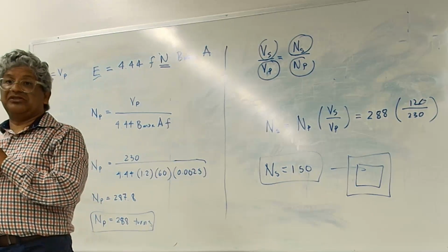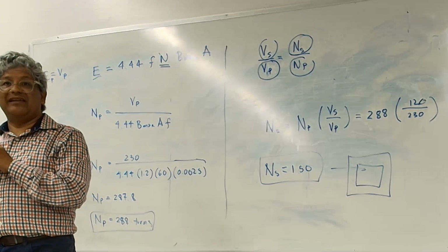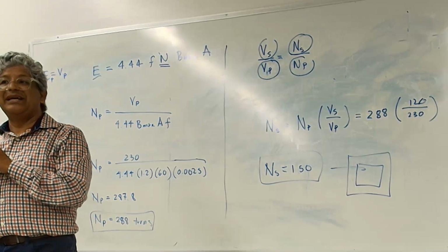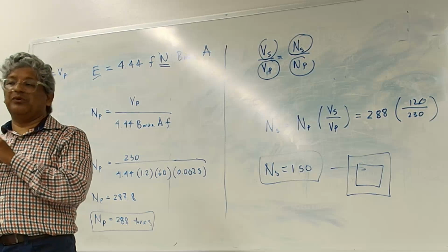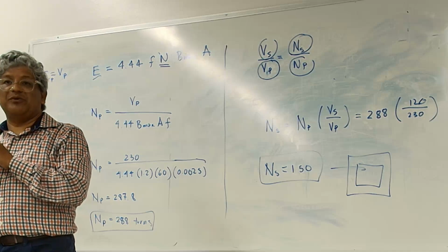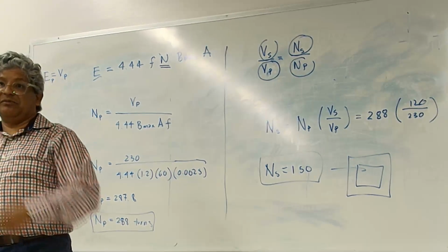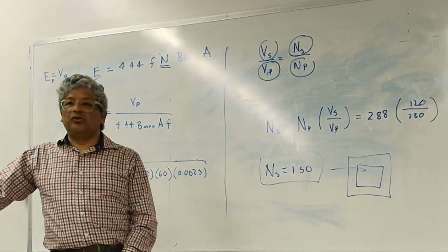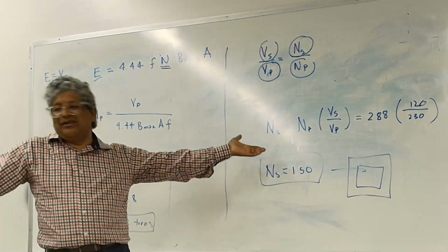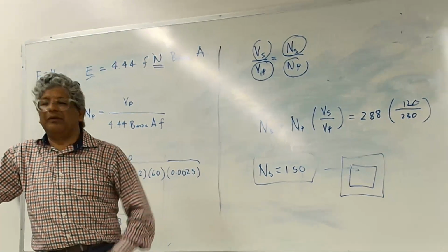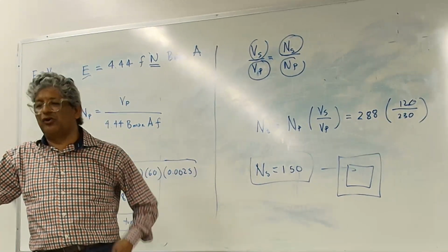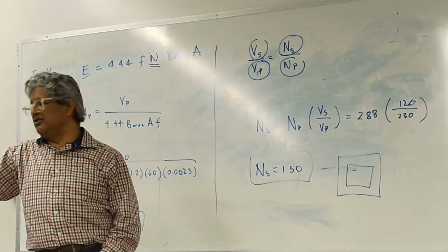And then the last one is a revenue transformer. If you're designing that transformer, you want it to be as precise as possible when it comes to current and voltage measurement, because that results in the power that it measures, which is the money that you're going to be paying the utility. So it depends on the application, and that's the equation they start with when they're designing a transformer.